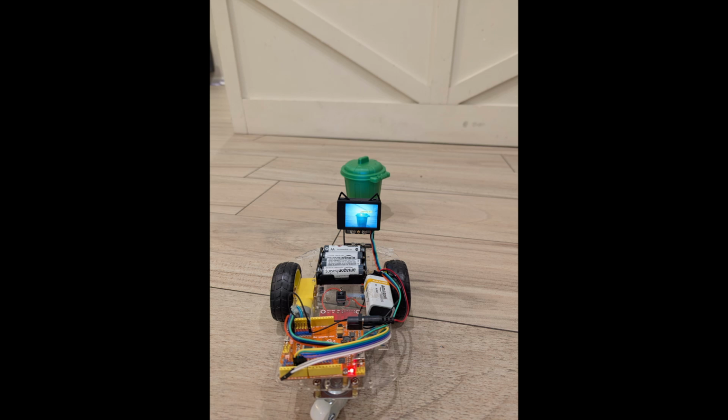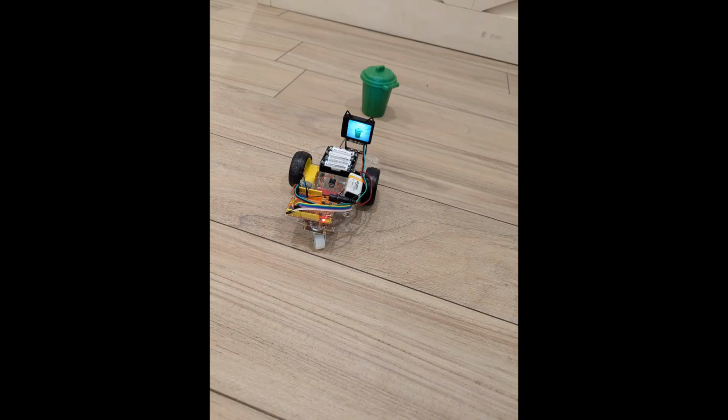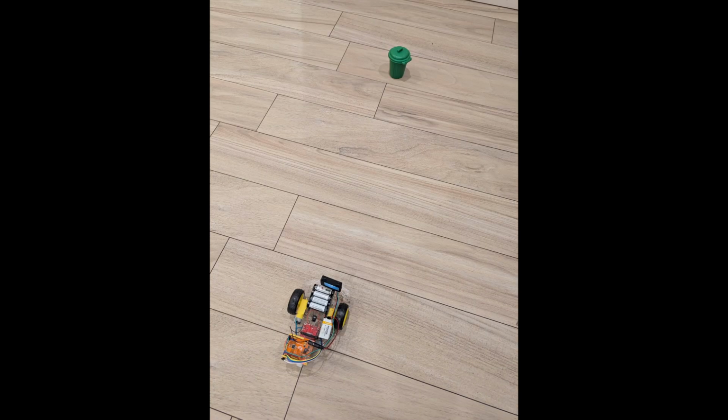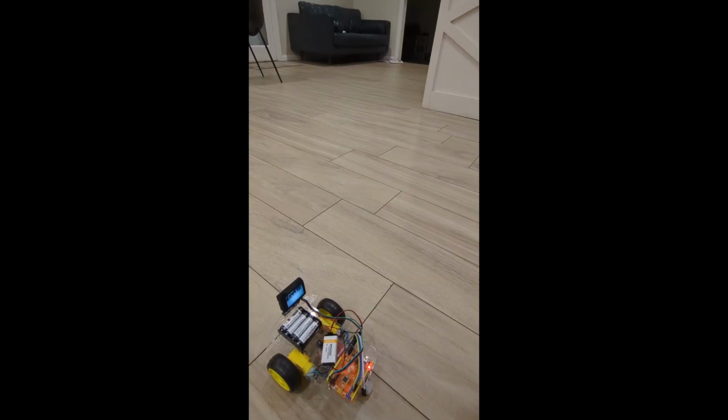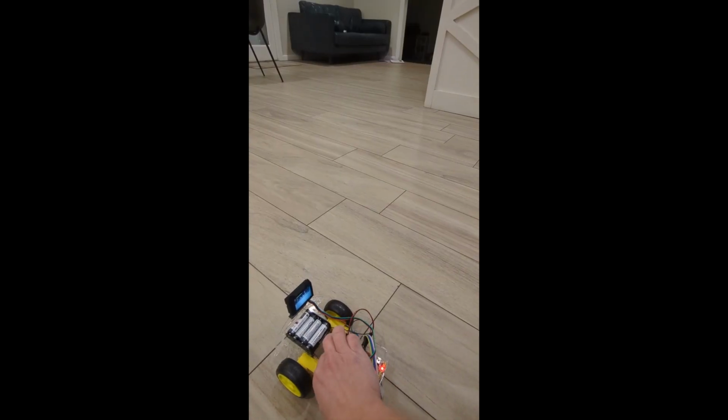You have to train your HuskyLens, giving it data in the same way that you want it to find your garbage pail. So it has to be in the same light, at the same height. You have to put the camera on the car, put it close, put it far, in the same scenarios that you want it to recognize the garbage.